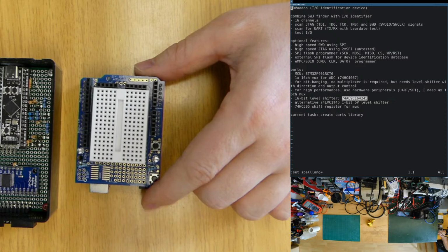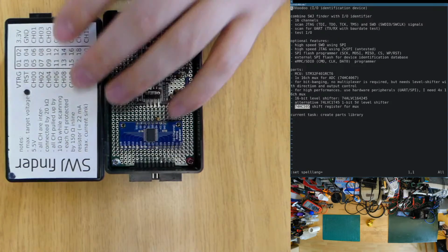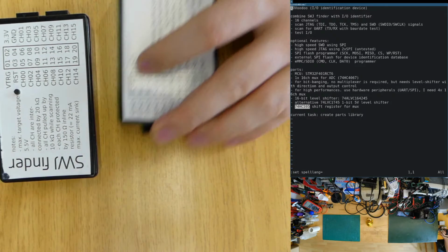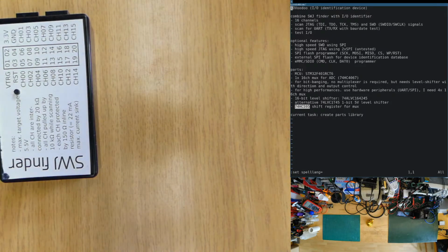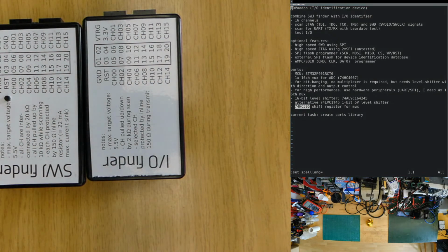These were the parts we're using. We need at least 2 of them. And then because there are too many pins for controlling the hardware multiplexers, 5 of them, I added a shift register. This way I can quickly send data to the analog multiplexer and control which channel I want, all 5 of them, because you need 5 lines to control one analog multiplexer.